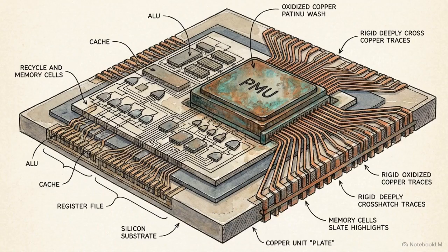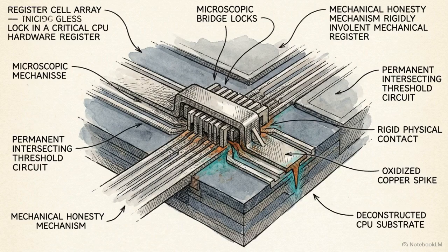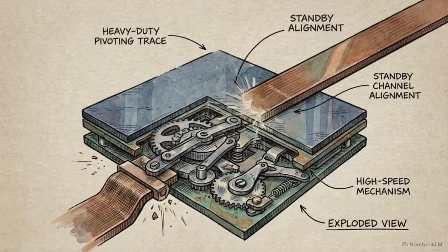The system monitors this using the CPU's Hardware Performance Monitoring Unit, or PMU, as a native zero-overhead drift sensor. The PMU inherently monitors cache line boundary evictions. It operates at the silicon level, reading data entirely below all software abstraction layers. Once the accumulated drift metric crosses a set threshold, the PMU fires a direct hardware interrupt. This triggers the tesseract maneuver.